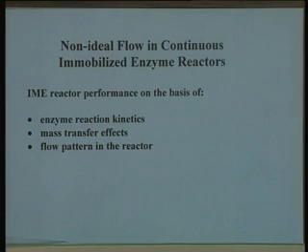And in all this analysis, we have assumed that the flow pattern in the reactor is either well mixed, perfectly mixed, that is the contents of the reactor are homogeneously mixed without any stagnant zones or any dead pockets in the reactor, or alternatively in the case of a plug flow reactor, the velocity profile of all the fluid streams is flat and it can be described by an ideal plug flow behavior.